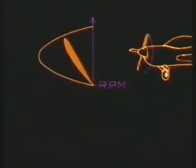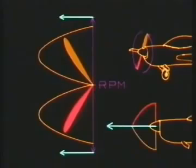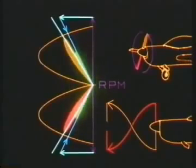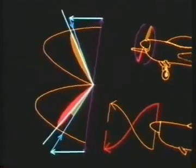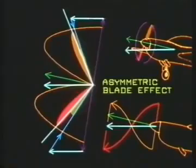Obviously, the RPM of an upgoing blade is the same as that of a downgoing blade, and in level flight, the distance they travel in half a revolution, their relative airflows, and their angles of attack will be equal. But the beginning of the takeoff run will be in a tail-down attitude, when the axis of rotation is no longer the same as the horizontal path of the aircraft. This produces the asymmetric blade effect.